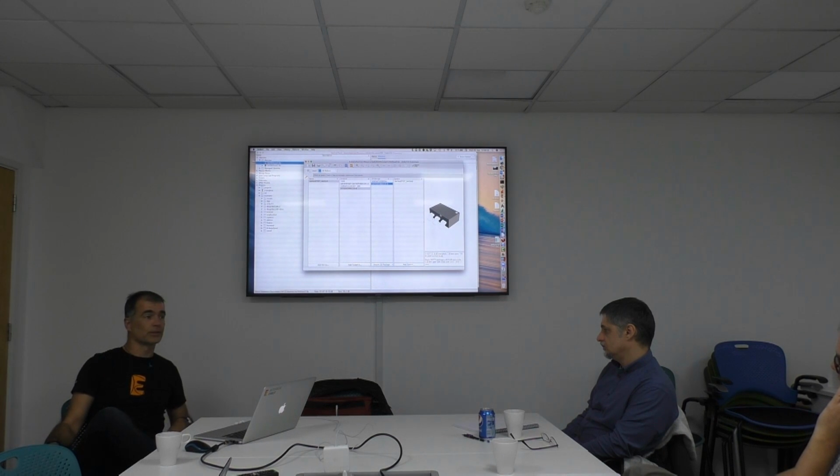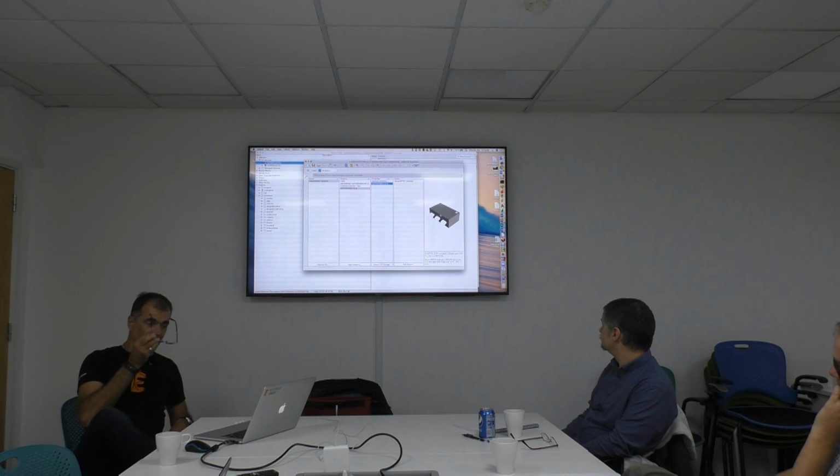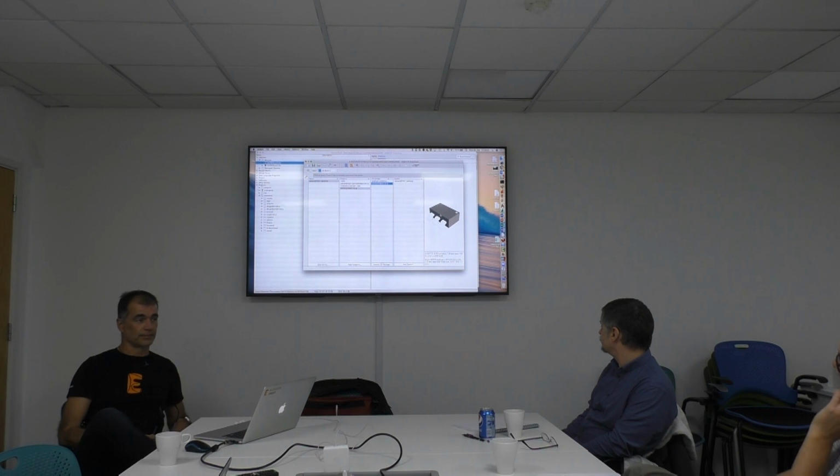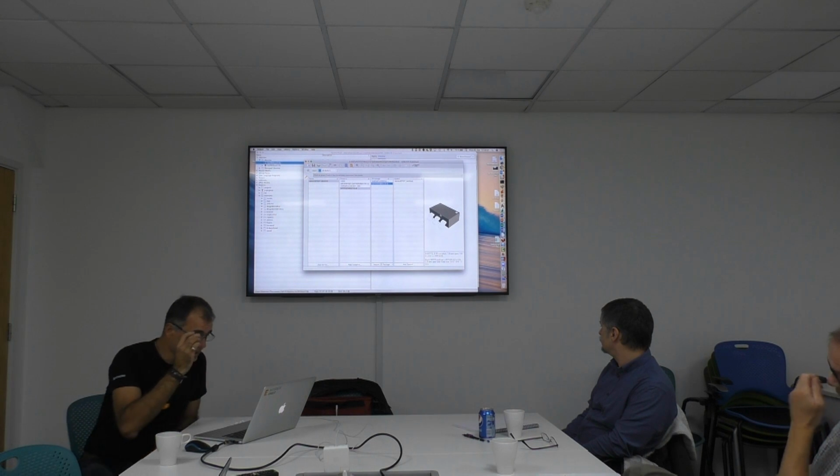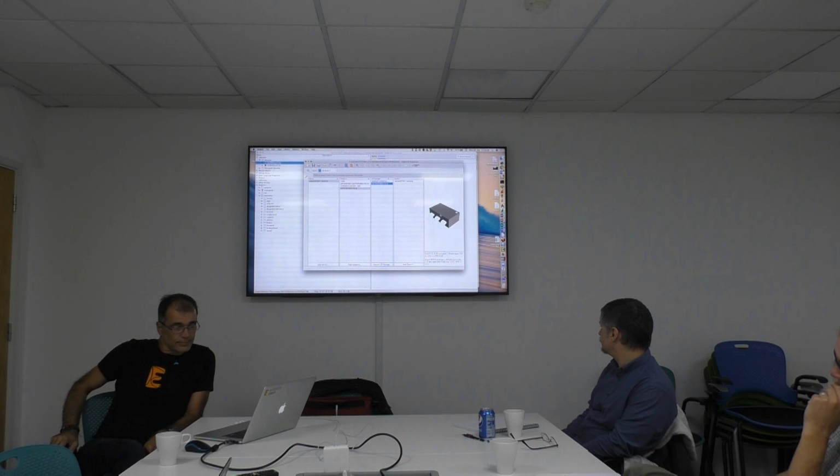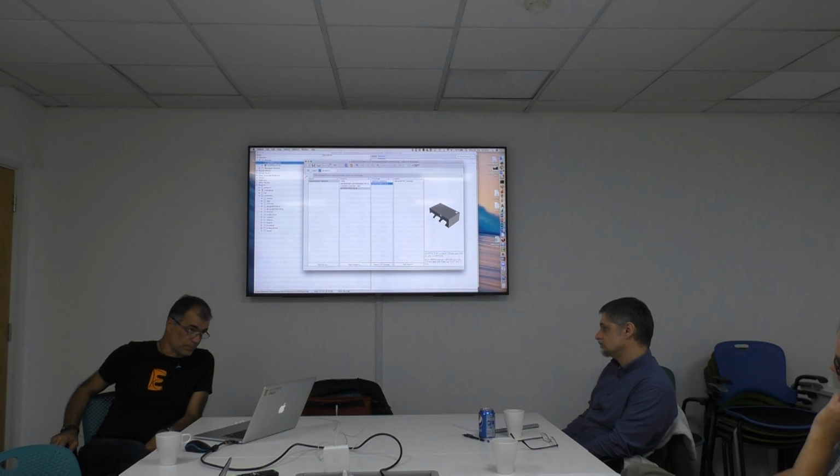That's the easiest way. Use the package generator. It generates a 3D model and it generates a footprint. That's the perfect way if it fits for you, and if it's okay that it is working with the IPC standards. So, okay, where to begin? I think we take the easiest way first and make the complicated later.